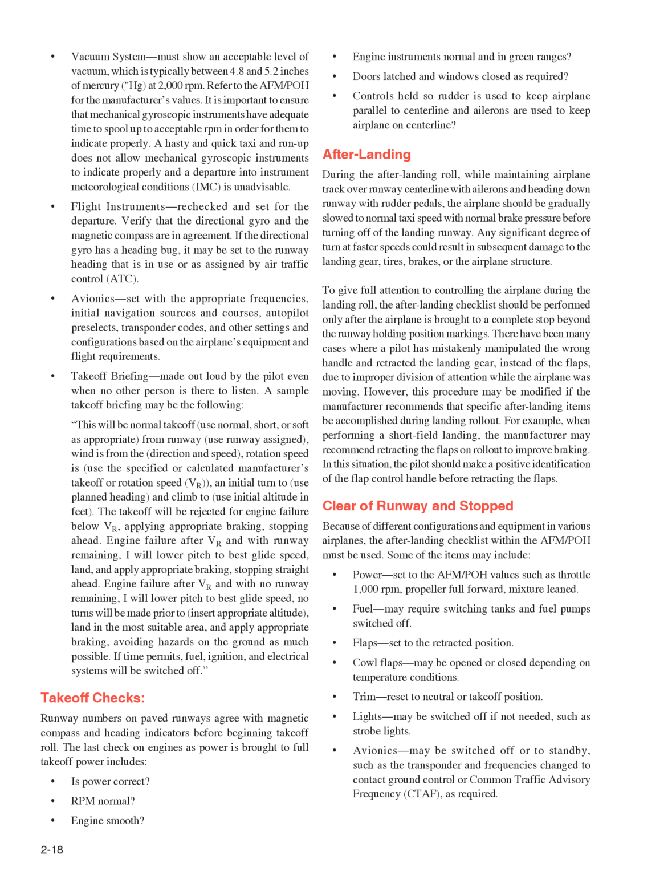There have been many cases where a pilot has mistakenly manipulated the wrong handle and retracted the landing gear, instead of the flaps, due to improper division of attention while the airplane was moving. However, this procedure may be modified if the manufacturer recommends that specific after-landing items be accomplished during landing rollout. For example, when performing a short field landing, the manufacturer may recommend retracting the flaps on rollout to improve braking.